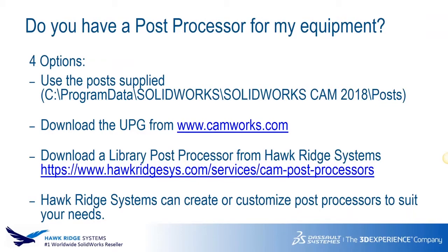The other thing that it adds is the ability to do indexing, pre-positioning, some people call it 3+2, for 4th and 5th axis machining. So a lot of times you'll be basically rotating your parts and keeping the brakes on the 4th and 5th axis locked, and just coming down and doing a drill hole or a pocket or a slot or something on there. The professional version will come with the indexing side, and again, we'll see an example of that a little bit later.